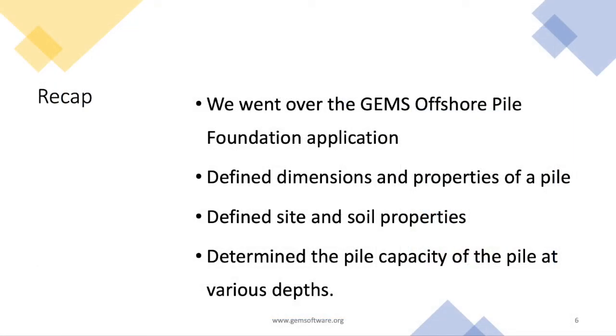To summarize, in this video, we went over the GEMS Offshore Pile Foundation application, defined dimensions and properties of a pile, defined site and soil properties, determined the pile capacity of the pile at various depths.